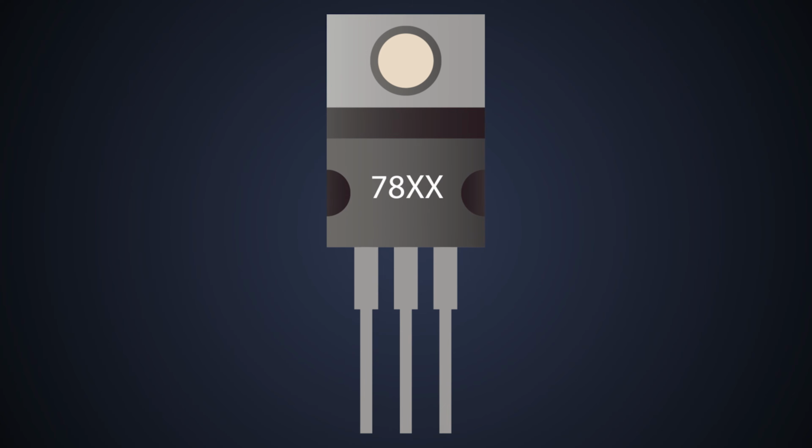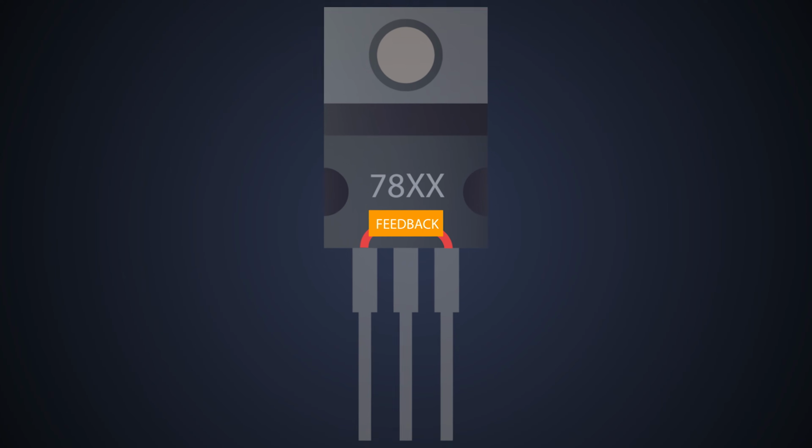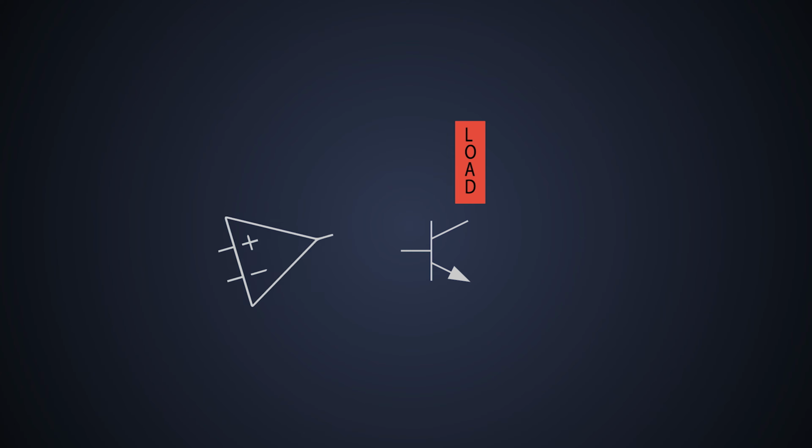Well, regulators have internal feedback loops, and that's how every regulator provides constant voltage or current despite input voltage fluctuation. So to get that stability, we need to provide some feedback to any discrete circuit which will give the regulated supply. So we need to bias the BJT such that it gives constant current. There are multiple ways to add a feedback path to this transistor. One of the most efficient ways to get very precise current regulation is by adding an OpAmp. That's right, this little triangular thing.